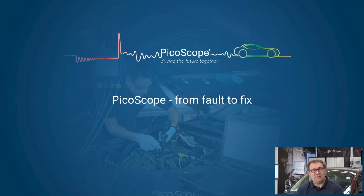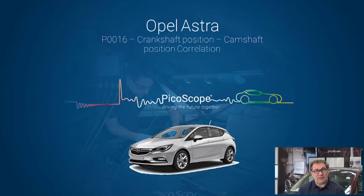Just to give you an example of where PicoScope is going to really help you with everyday diagnostic problems that, as I just said, are going to be every day within a workshop. So I'm going to start with cam and crank position sensor correlation. And often we get told that this is a main reason for buying a scope. So I'm just going to take you through the process, what we look out for, and really how we look at timing using the scope.